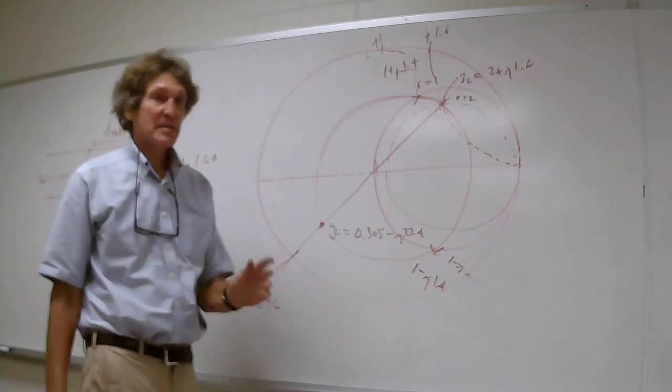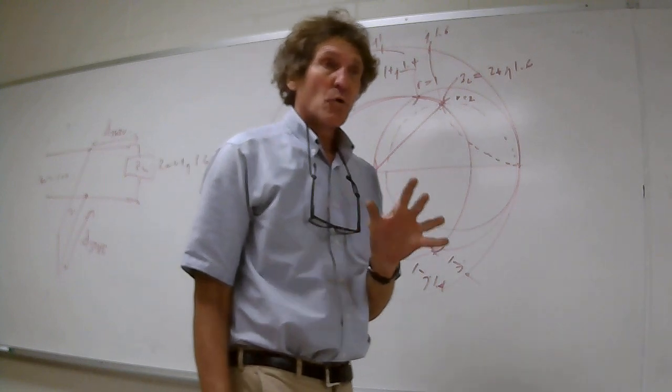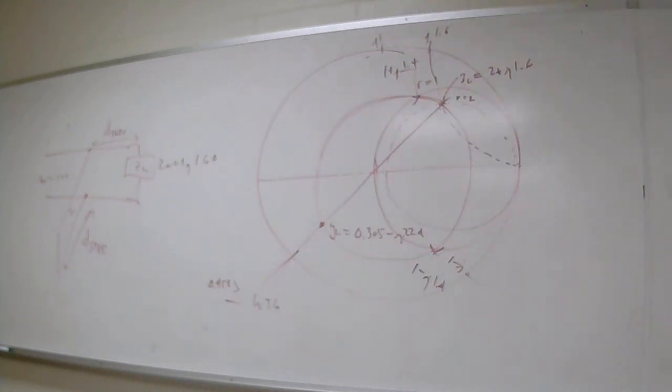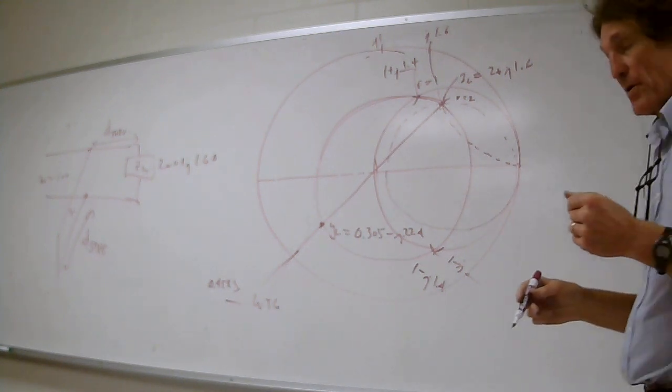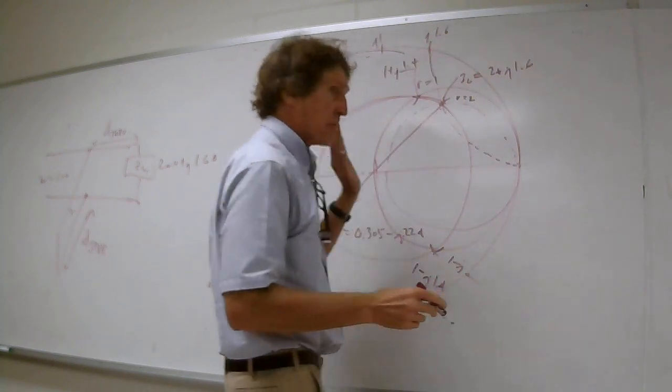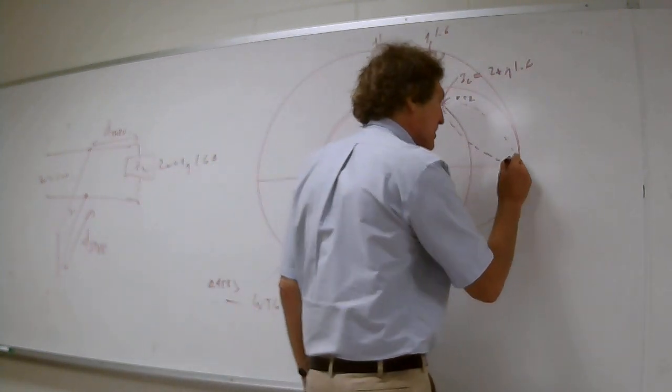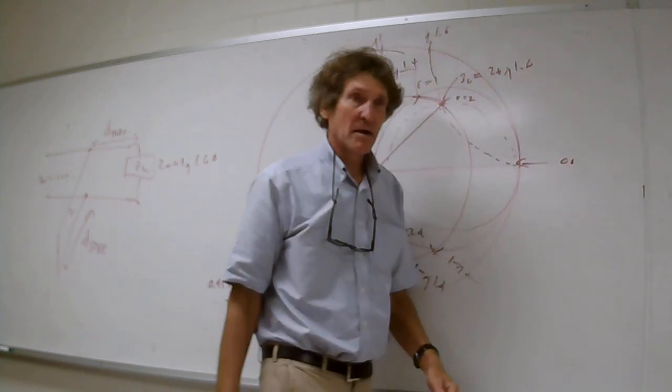Now, here's where everybody pays attention. We're in the admittance domain. We have a short now; I'm going to draw it over here. I have a short circuit. We're going to assume same characteristic impedance. ZL for a short is 0. Normalized is still 0. YL for a short is infinite. Do you all agree? Now, think about where you come in. Where is the infinity point? To the very right, right here. So we're coming in here. You all hear me?